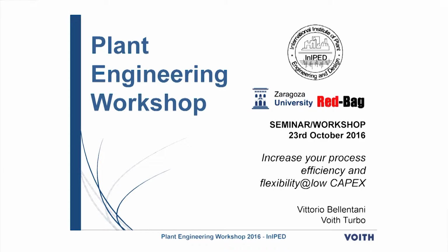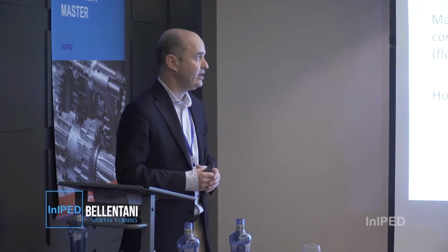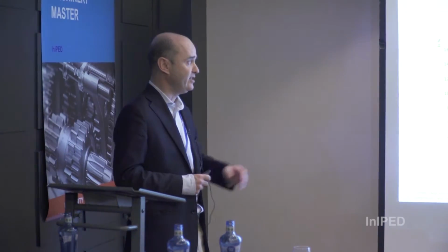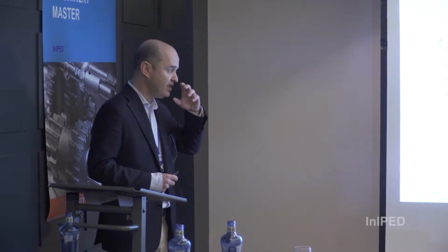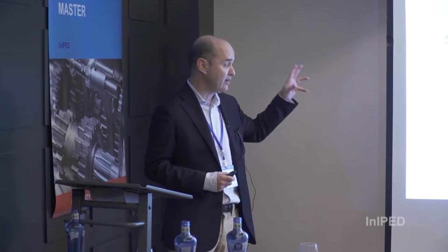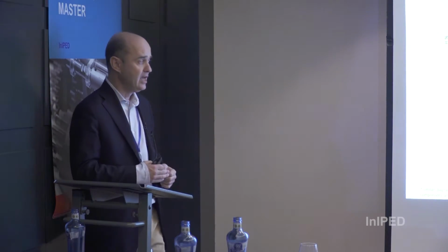It's about flexibility, efficiency, and low capex, because these solutions offer a reasonable capex amount for good flexibility solutions. So we start from the fact that in the oil and gas industry, very often pumps and compressors cannot be run at a fixed point, but some flexibility is needed. Now, how can we achieve this variation in the output of pumps and compressors? We start here with the example of a pump, but similar considerations apply to all centrifugal machines, which means also centrifugal compressors and centrifugal fans.